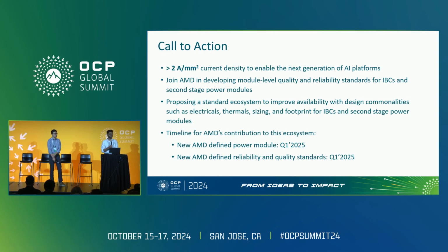Thank you. Hi, I'm Rob Chiacchia with Ridge Tech. Do you see room or a need for these two-phase modules with TLVR and non-TLVR magnetics? Yeah, so I think, especially as you have heard, with the challenges with HBM3, HBM3E, and HBM4, the PDN noise tolerance is getting even tighter. And on the next generation AI compute platforms, we do really see a need for the ability to meet even tighter transients, right? So we foresee it would always be a combination on the platforms, where you have I/O or some rails which are not really tight to meet the PDN.